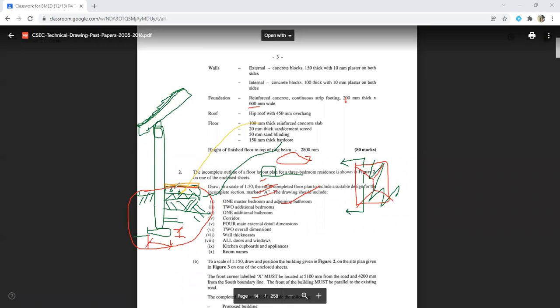concrete. The screed is basically a thin layer. Typically, when they spread the concrete, when that hardens, it is normally not very smooth. There are times when you have dry spots, you have rocks, stones, or aggregates protruding out of it.